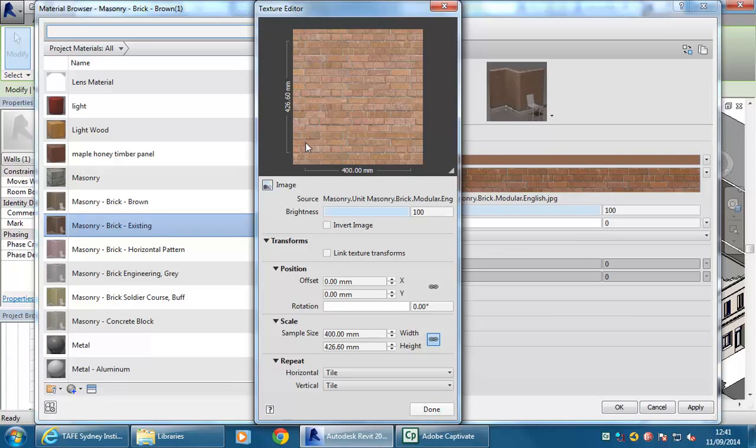And then looking at the number of courses there, you can make that a real world size. Unlike the concrete, where I'm basically just sizing it to get the look I want, with something like this, you'd want to make it the size of a brick in real life, or close to it. Maybe a little bit overscale, because it's in the distance. So if I count, 1, 2, 3, 4, 5, 6, 9, 10, 11, 12, 13, 14, 15, 16, 16 courses within that distance there.